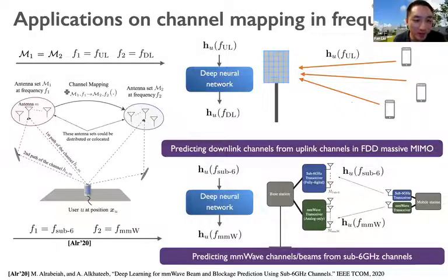Okay, many thanks. I will have a final question for you. Comparing to the current 5G new radio standards, which adopt reference or pilot signals to do beam training or beam tracking, how much overhead can be reduced by using your sensing assisted communication? That is the first question. And the second one is, do you think that sensing assisted communication is able to eventually help us bypass the general channel estimation procedure?